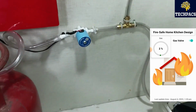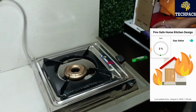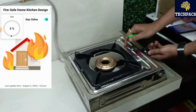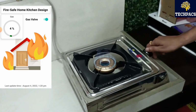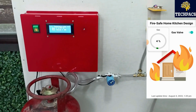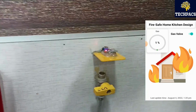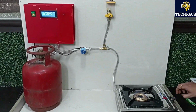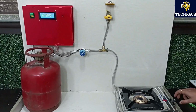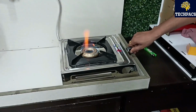So the flow of signal is, like here we can see that the burner would turn on. As soon as we give the instruction from the application, it is detected by the IoT server, from which the control box instructs the rest of the components, and this is how the entire signal flow works in this project.